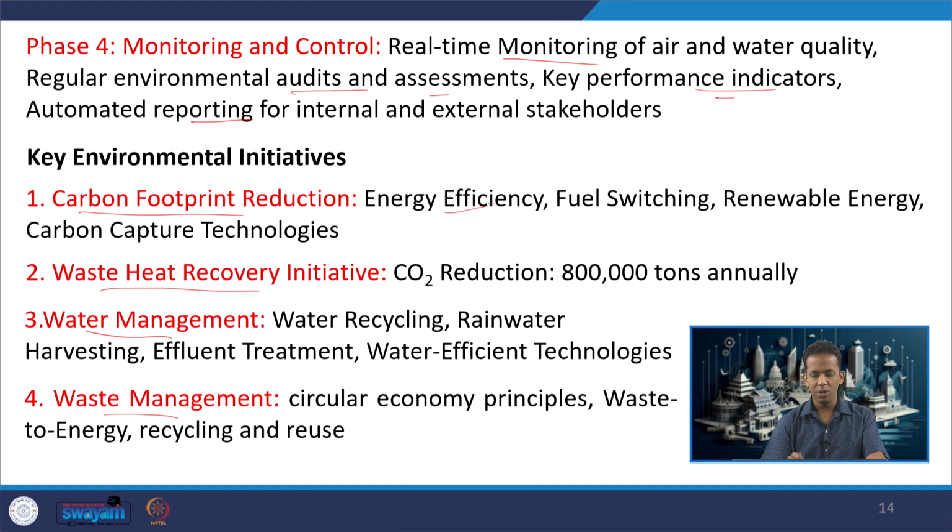For example, energy efficiency was increased, and fuel switching was done, like switching from fossil fuel based to renewable energy based fuels, or from the poorer performing fuel to the cleaner and better performing fuel. For example, if you are using coal for burning, instead of coal if you use coke or pet coke, it is a cleaner fuel. If you use natural gas, it is a further clean fuel, though it is a fossil fuel, and if you use renewable energy, it is also an alternative source of energy. Then carbon capture technology also contributed, so all these factors overall helped reduce the carbon footprint.